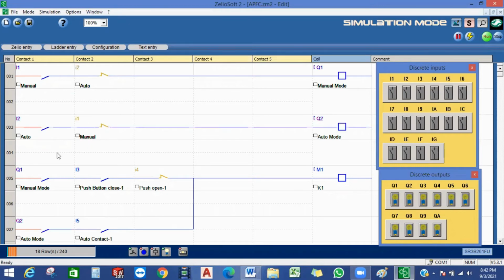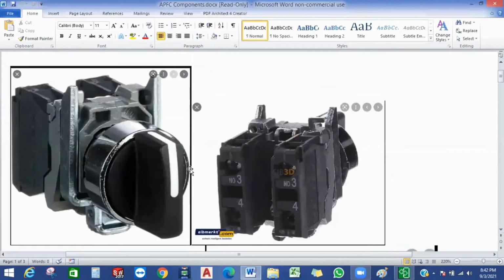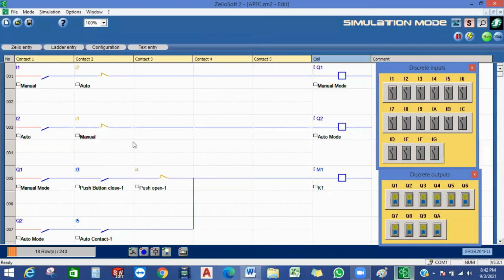And in manual mode, this is our switch. When you turn this left, the contact block is on this side. This is giving power going to this. But turn right, and the auto mode is running. So there will always be either auto or manual. So here we represented that by one interlock, which means if you try to close both switches, you see what happens.